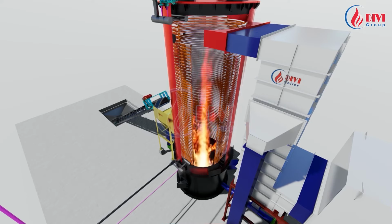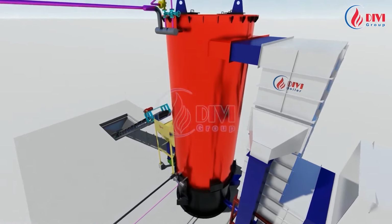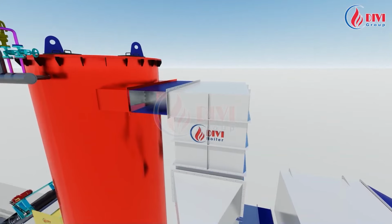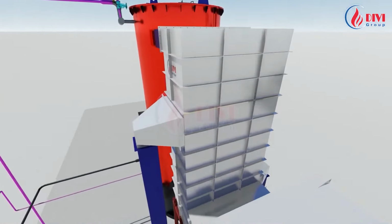Hot smoke going to the top of the furnace will continue to enter the gap between the 2 spiral tubes and exchange heat by convection with the tubes containing oil inside. The smoke stream will go down and up through the narrow gap and exit to the rear heat utilization device. The smoke stream, after heat exchange in the thermal oil heater body, will have a certain amount of excess heat left. So the fluidized bed thermal oil heater system will be arranged with an additional air preheater behind to make full use of this excess heat.